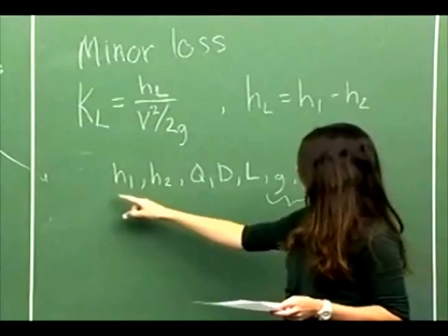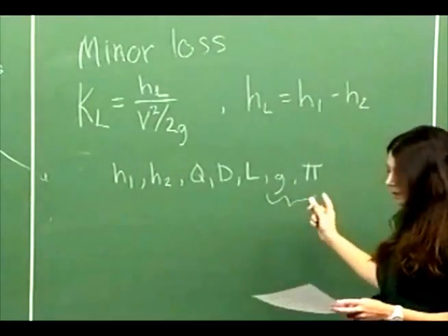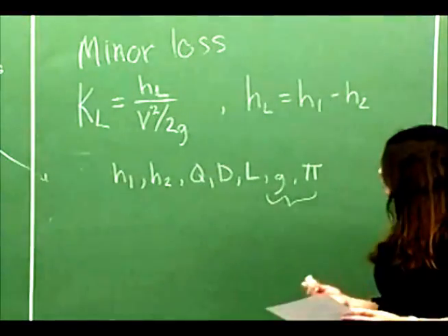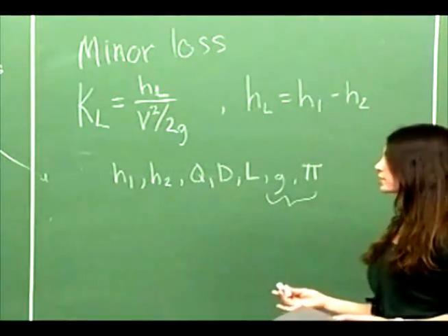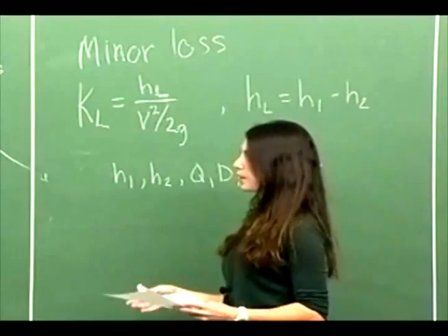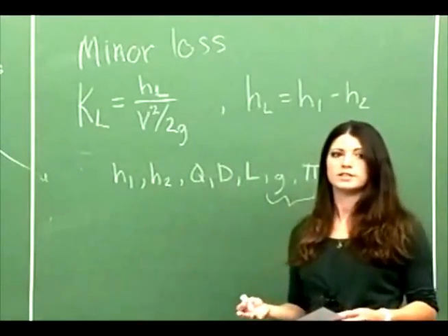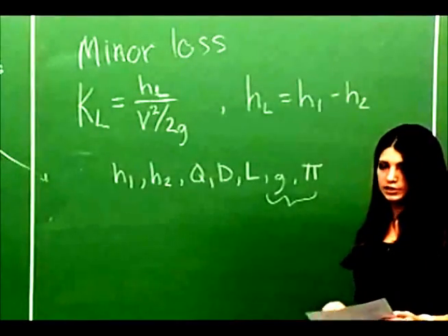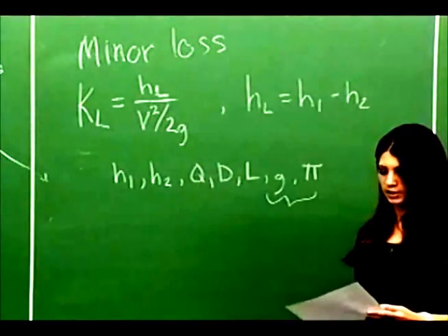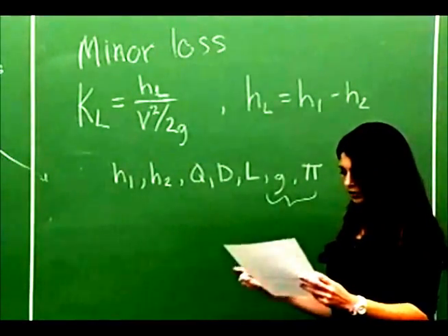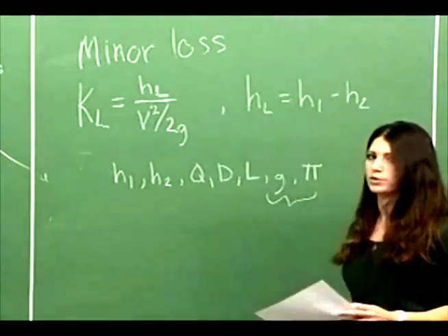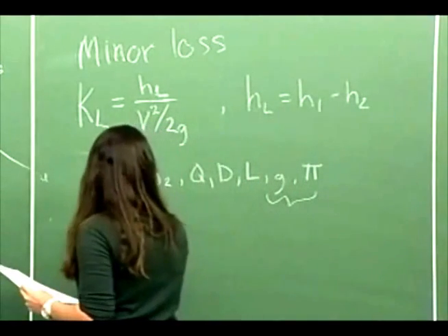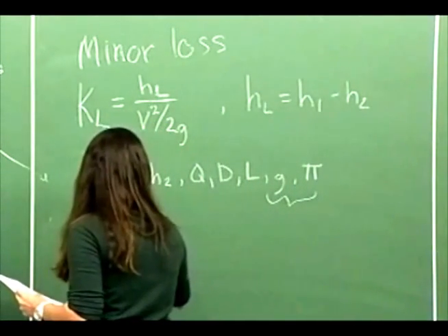And once you have your friction factor in terms of all of these quantities, you'll be looking at the root sum square expression to express the uncertainty of the friction factor. So I'm sure you guys have seen this before, and if you need a lot of detailed information on it, there's more information on the website. There's actually a whole document that goes over the uncertainty calculations. But I'm just going to show you a general formula here to give you an idea of what this root sum square method is. So to get the uncertainty of the friction factor,